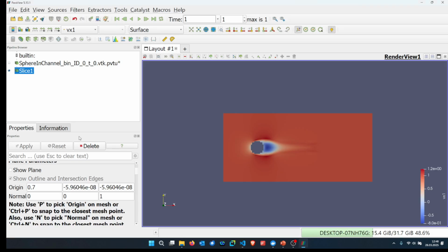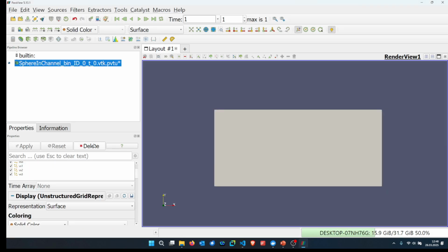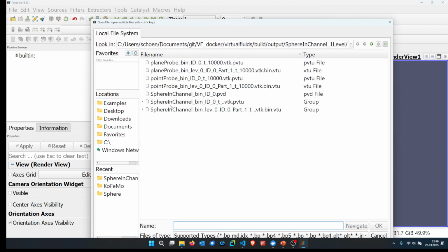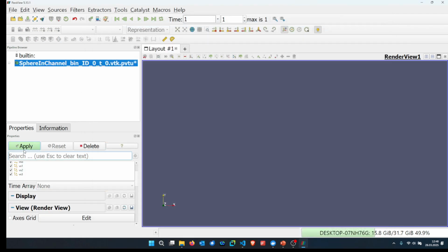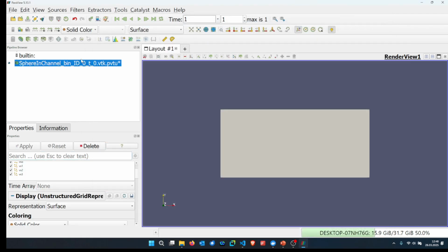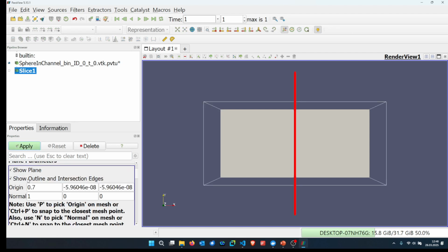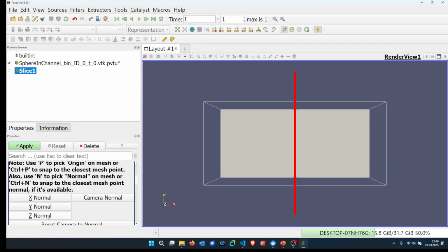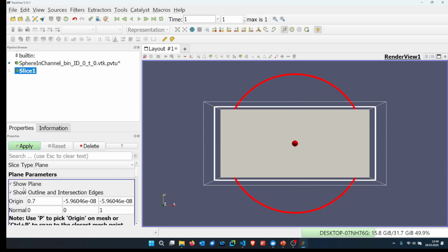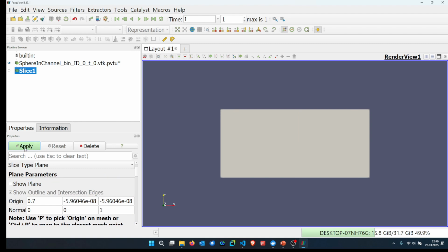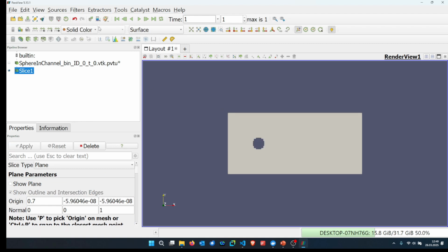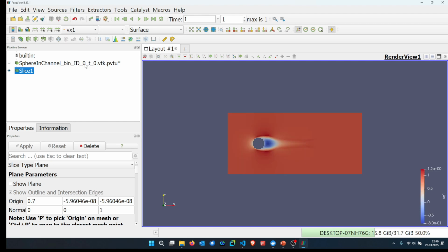There is some tradition in lattice Boltzmann with the Smagorinsky models, that the Smagorinsky model is often just added so that the simulation does not crash. So on top of BGK, you can make BGK stable when you add a Smagorinsky model. But I think the actual stability is not really the issue for which you asked for the turbulence model. Or do you correct me?